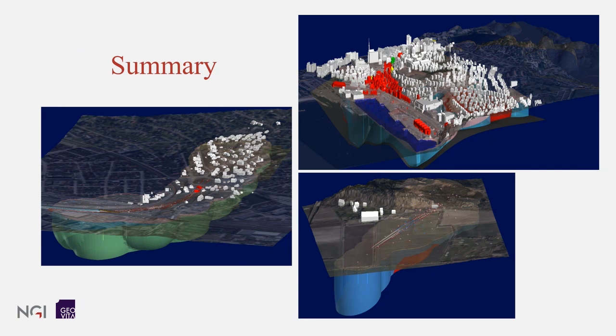I would also say you get the most out of the model by setting it up early in the project. And then you can enjoy having good illustrations for meetings. And it is also very nice to get the layering done in some sense, because then you have a best guess of the layering based on the currently available information. And you don't need to go back and forth for each new cross-section you decide to do calculations on.